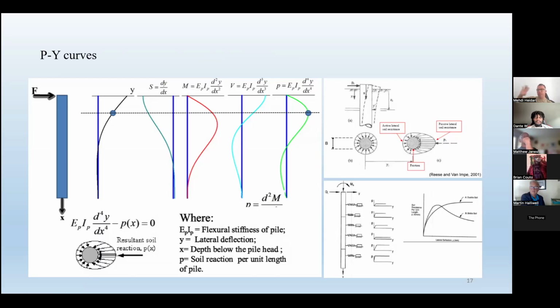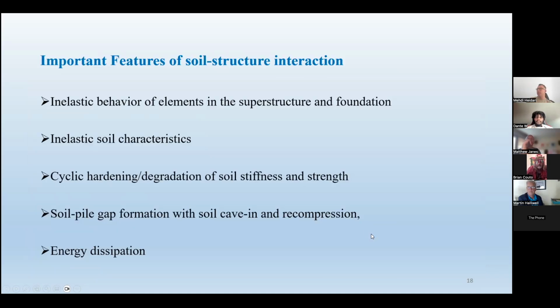But this is not an elastic fully plastic curve. This is a nonlinear curve, and I did some research on that topic, and it can have a significant effect on the response of the pile, the deflection that you receive, and also the internal load that we can estimate. Even the initial portion, which is the K0 number, varies with depth. Different types of soils have different conditions, but our main goal was to not only estimate but properly simulate this when it comes to analysis.